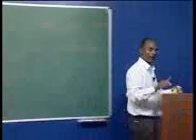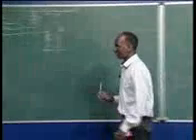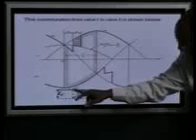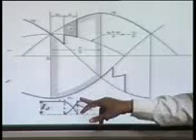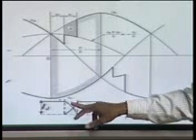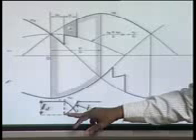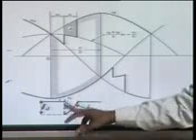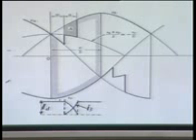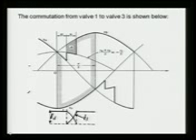We will see more detail about this. The graph which I have shown here is also very tricky. You can see the current from 1 going like this, and 3 picking up like this. You can ask why it is not like this, and why this is not going to be this one. We will derive the characteristic during this conduction period, how the current changes from one valve to another valve, later on in the same lecture.